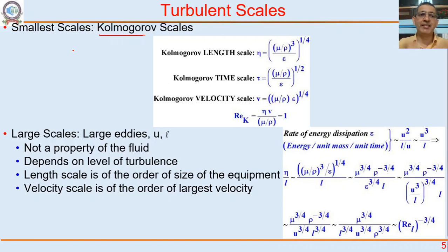The amount of energy that we give the fluid decides how much turbulence we have. So he categorized the energy we put in as power dissipated per unit mass, denoted by epsilon.